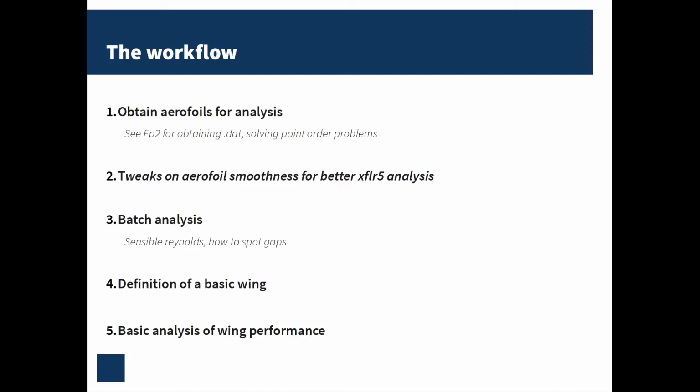So the better your data at this stage, the more accurate the data is going to be at the end stage. You can speed things up tremendously at this step, but being more strategic with how you do your analysis at the entry stage in the batch analysis is going to largely impact not only the accuracy of your results, but the range of results that you can get. For example, if you were to only set a -5 to 5 degrees angle of attack analysis window on your airfoils, then during the stability analysis, if at any point a particular case were to go outside of 5 degrees, it would not be able to interpolate that, and that would give you no data at all.